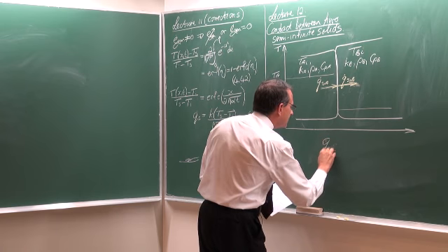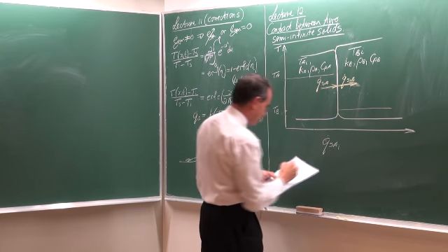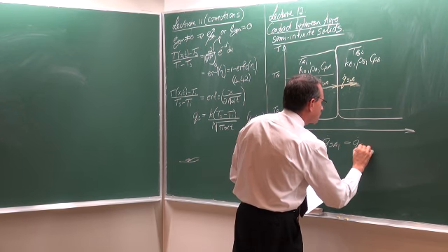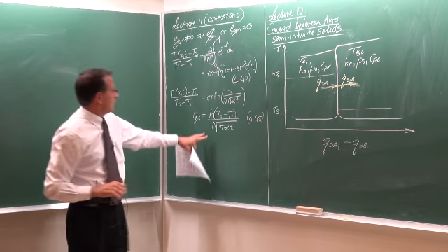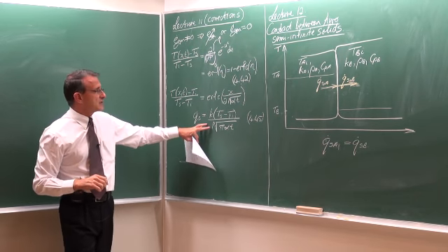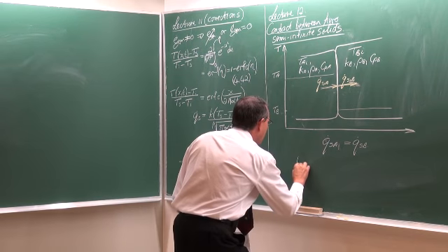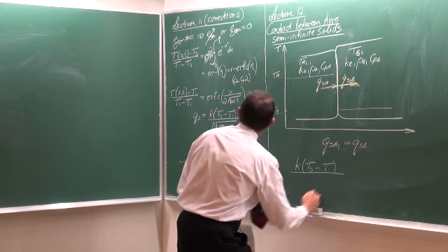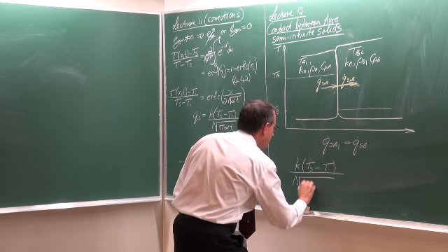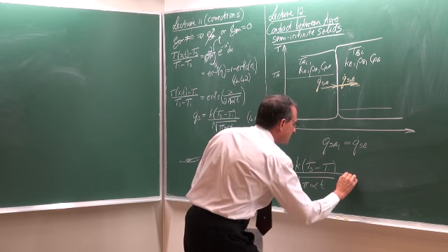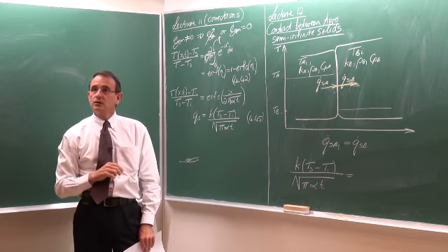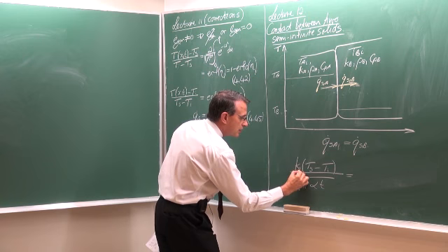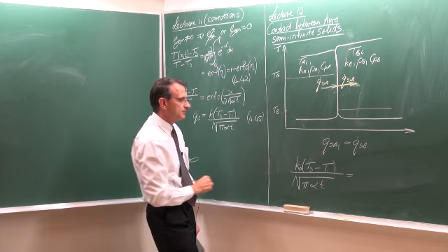And what we now can say is that the heat flux on the surface of A is equal to the heat flux on the surface of B. And with the previous lecture, we've seen that the heat flux can be written as K multiplied by Ts minus Ti divided by the square root of pi multiplied by alpha t is equal to, but we have to distinguish it from the right-hand side, where this K would be the thermal conductivity of body A.